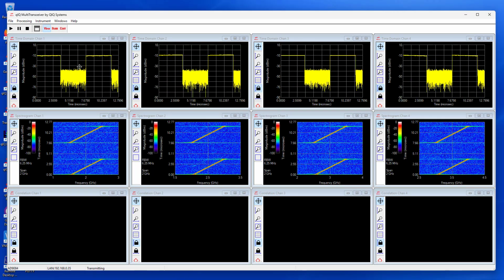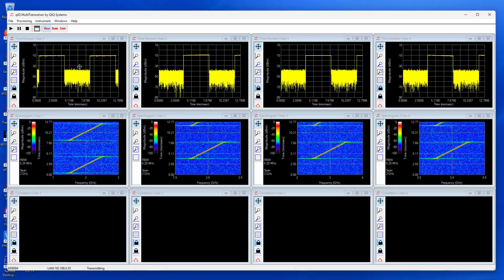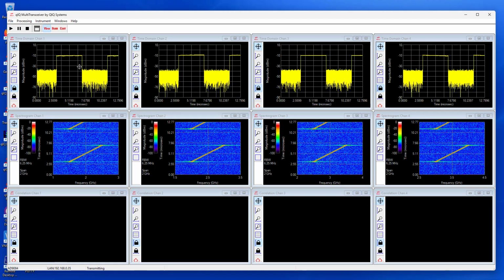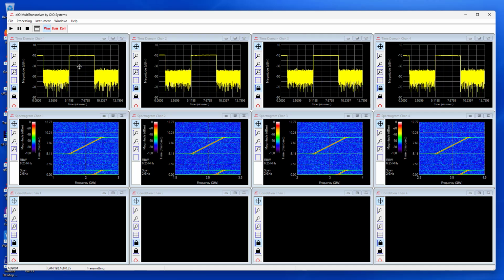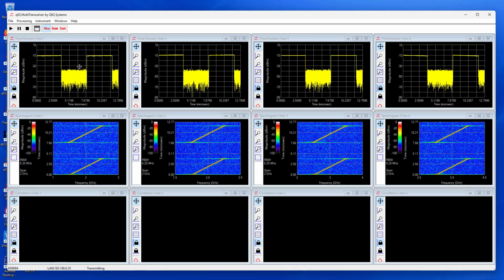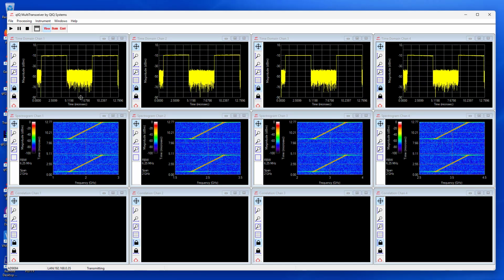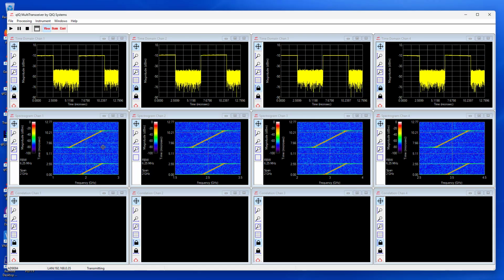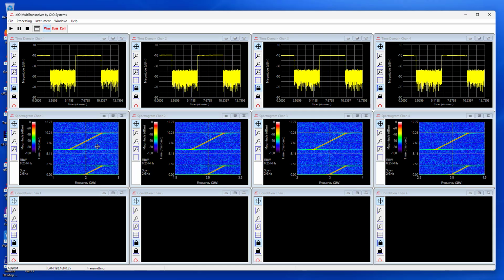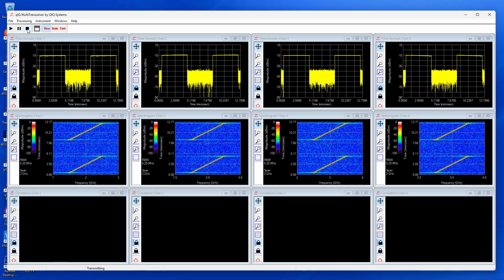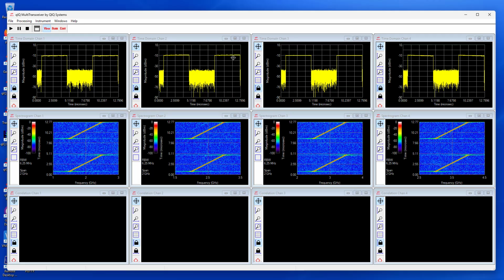This particular firmware that is in the 9084 eval board does not synchronize the captures of data with where the transmit waveform is in playing the transmit waveform. So it sort of runs open loop. It just acquires whenever we ask it to acquire, but there's no synchronization going on there. But you can see that the captures of each of these channels are all synchronized in time.